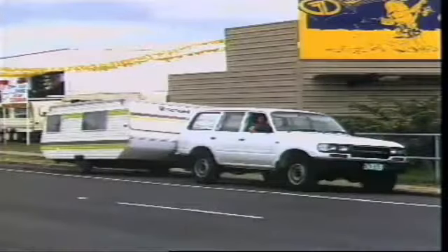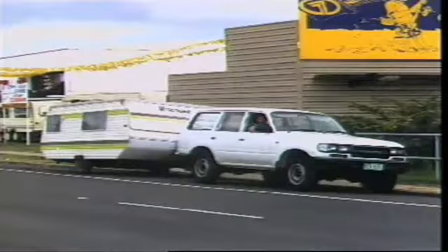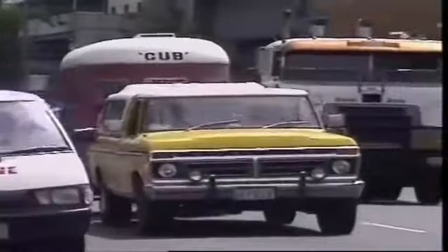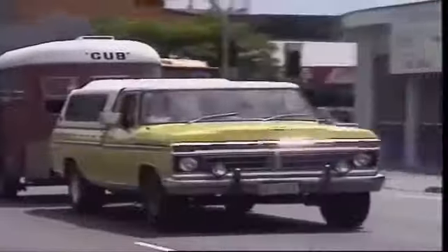This section examines electric brakes. Trailers and caravans towed by light vehicles must have a braking system if the trailer gross mass exceeds a certain value. An electric braking system is commonly used to activate the drum-type friction brakes on the trailer. Braking effect can be increased or reduced by the driver adjusting a control unit to suit the load on the trailer.